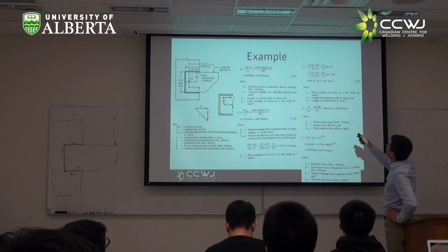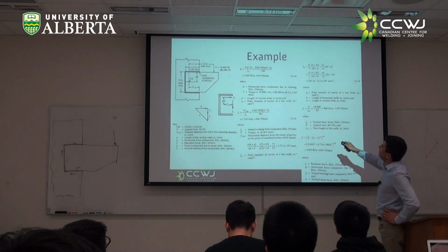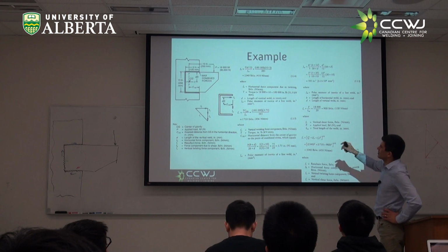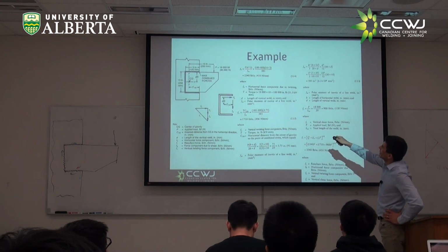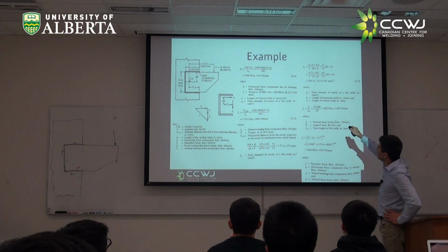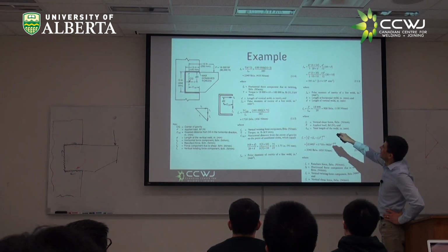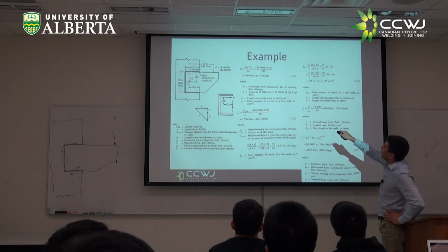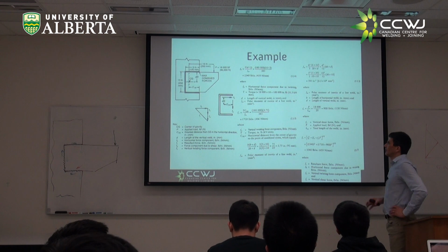And this is what they calculated here, right? So I'm waving my hands here. Mitch is going to do this. But you have this force that we have a formula to calculate. We only needed to know the polar moment of inertia. We have another formula to calculate that. And with that, we can calculate a horizontal force, right? And it says this is going to be this force per unit length, 410 newtons per millimeter. Fine.